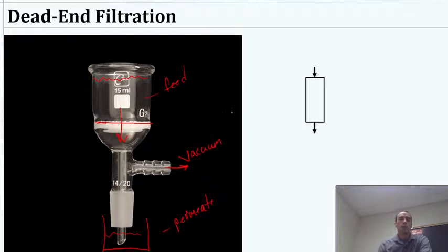And one thing to note here is that for filtration, if you're going to use the vacuum, you have a hard pressure limit equal to atmospheric pressure wherever you are, right? So if you were applying this vacuum and you have a pump that was really, really effective and could get to a true vacuum pressure, so absolute zero, I suppose, then your pressure difference is equal to exactly what your atmospheric pressure is.